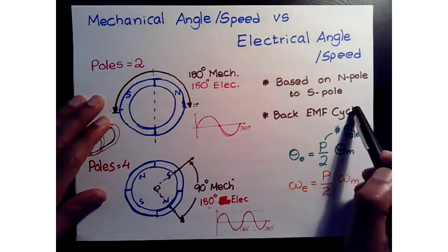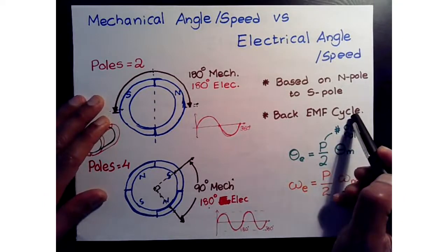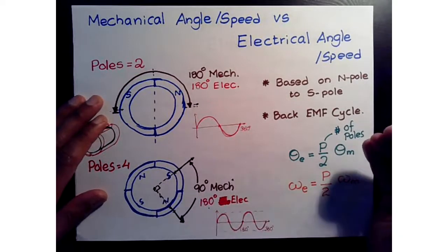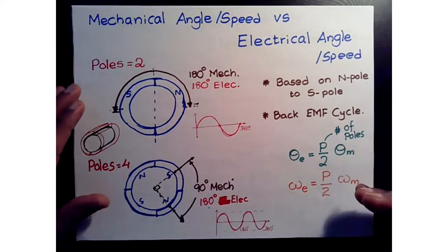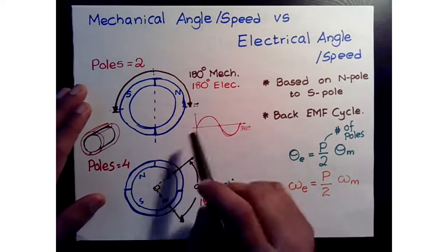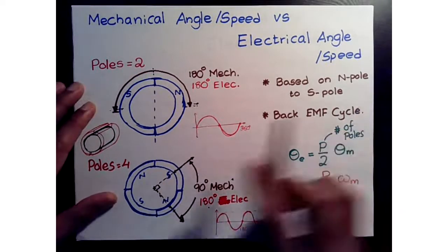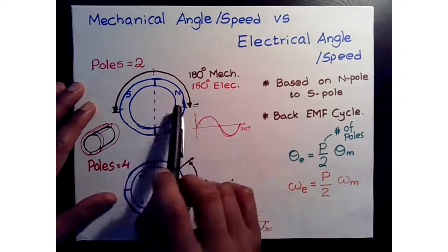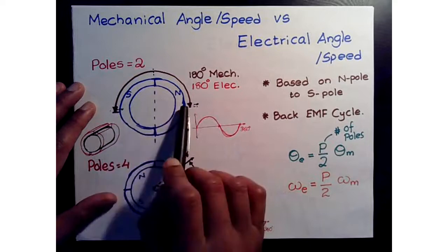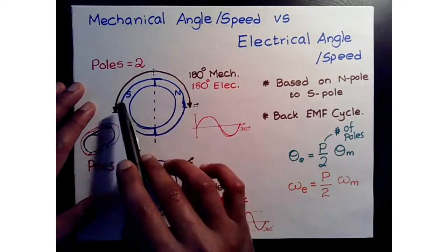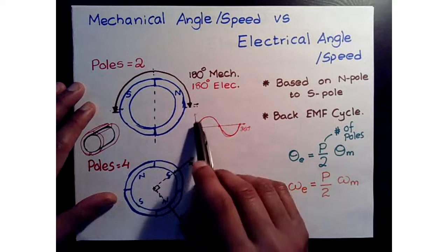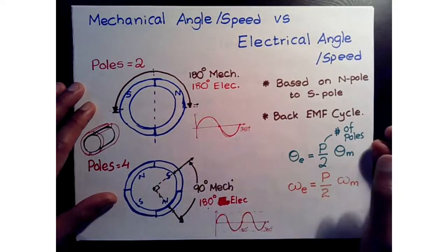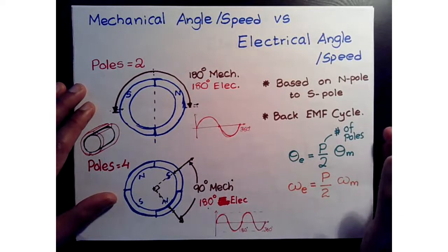Now, this can be viewed from the back EMF perspective. For example, if you looked at the back EMF across a certain winding, or a phase to phase voltage, when it's not connected to an inverter, you'll see that when you spin one mechanical cycle, if it's a single pole pair or two pole motor, you will see one full back EMF cycle for one 360 degrees mechanical rotation.